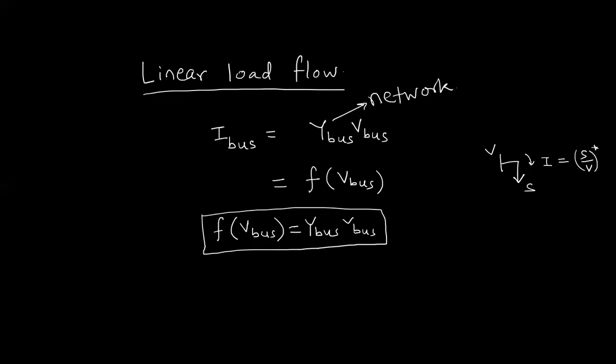So what we are doing basically is linearizing that equation and solving it as a linear equation. In the case of transmission systems, you may be familiar with something known as DC load flow. We are treating the AC circuit approximately as a DC circuit.